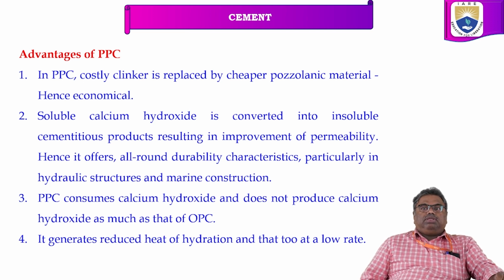Permeability characteristics will be improved in the case of PPC cement, right? So it offers greater all-round durability characteristics, so we can use this type of cement in hydraulic structures and marine construction. The third one is that PPC consumes calcium hydroxide and does not produce calcium hydroxide as much as OPC.